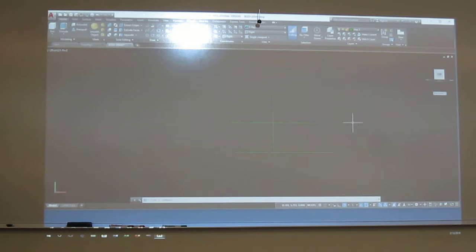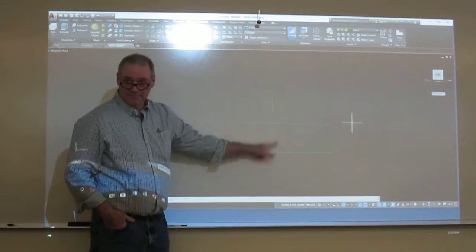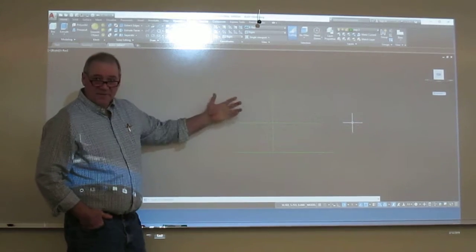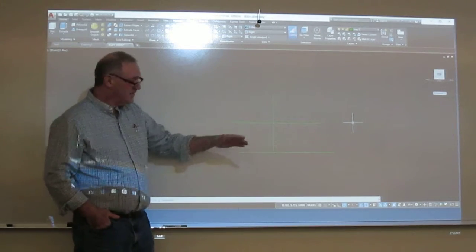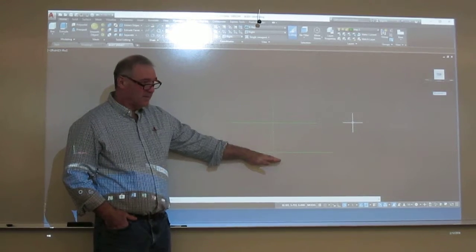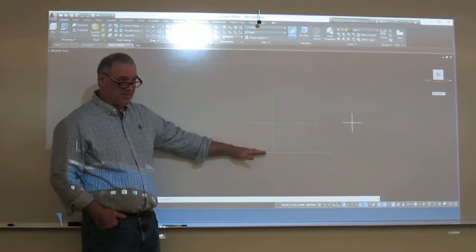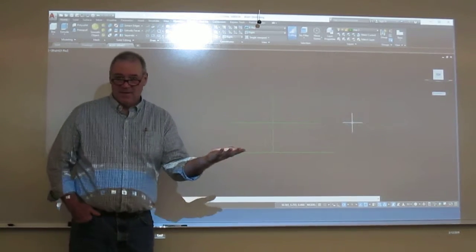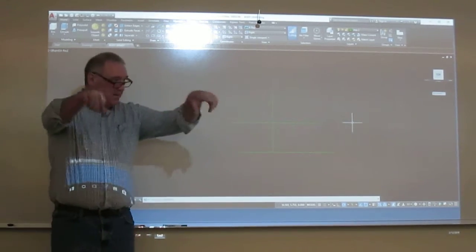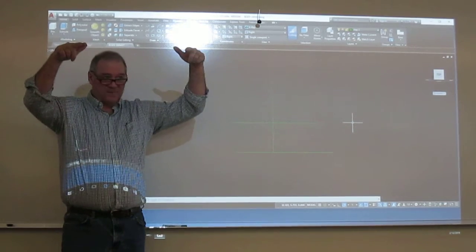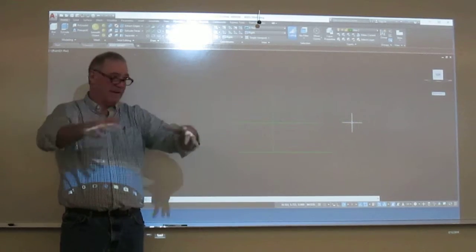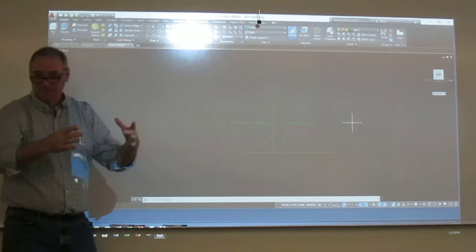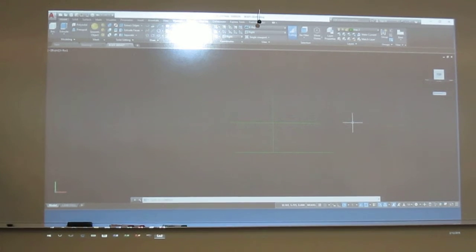Okay, you ever see that? Now, here's your same datums. Right here, same datums. What did I do here? I wanted a surface perpendicular to my datum because I'm going to use the extrude command. Where does everything base off of? Off the bottom. Okay. Now I can't really use revolve because you have the bottom piece with the flanges, the top pieces with the flanges, and then we have really a collar in between the two, right? So I don't have a constant shape on the way up.